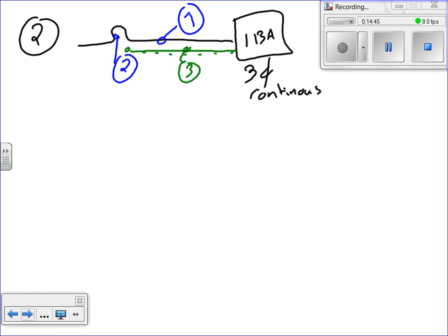What does continuous mean? Fully loaded, running for 3 hours or more. Look at these lights. A good example of this, guys. You came here, Brad, you were here at 6:15 when your wife kicked you out of the house. From 6:15 until 9 o'clock now. In a few minutes, it will be 3 hours, and they will be on until probably 4 o'clock. These lights. That's a continuous load.